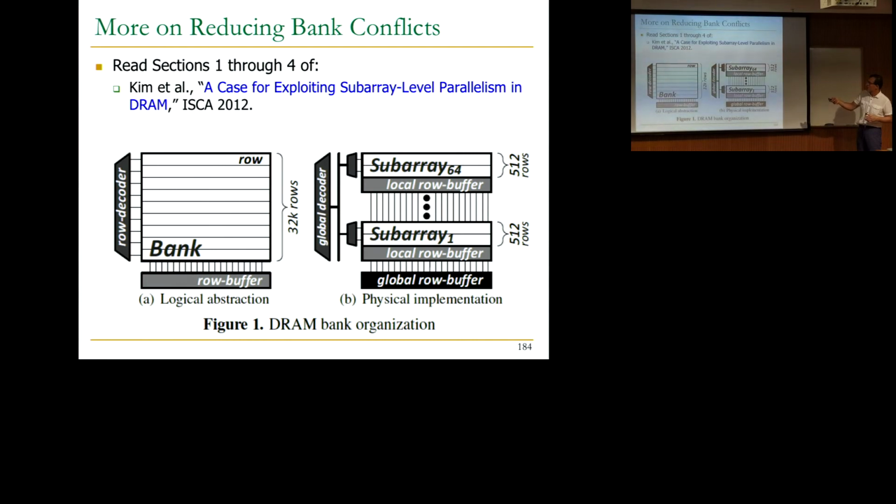it has these local bit lines. Whenever you want to activate a row, you go through this global decoder, latch the address, and that drives one of the rows in one subarray. When you activate a row, it gets sensed locally. So you have this big local row buffer. Now your interconnect is much shorter, of course, over here. As a result, the latency is much better.